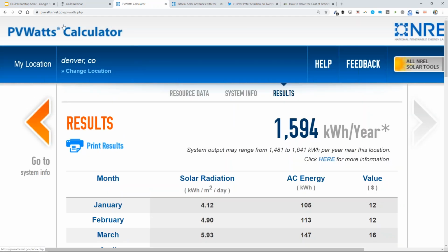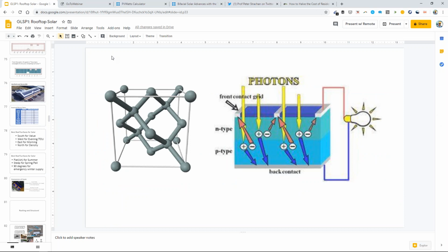Yeah, but what I want you to take away is, while yes, a more productive array is almost always more cost effective than a less productive array, there are weird edge case scenarios that you aren't crazy to consider. One of them would be in a remote location, hanging some panels vertically to mitigate the impact of snow shedding. Especially if it's a remote location where on-site backup power or emergency power is desirable. So feel a little confident to be creative with your solar panels. Often nowadays, the solar panel itself is not the most expensive part of the project. Back in the day, solar panels were $3 a watt. That's 10 years ago. Now they're 44 cents.